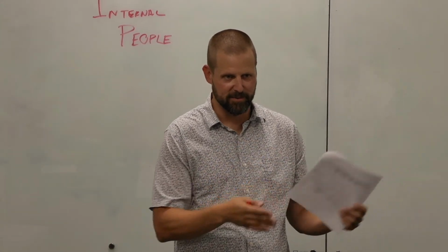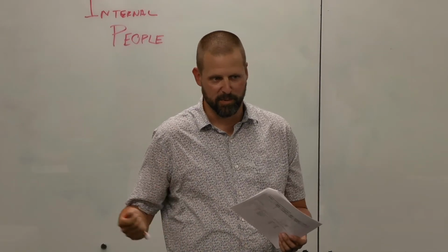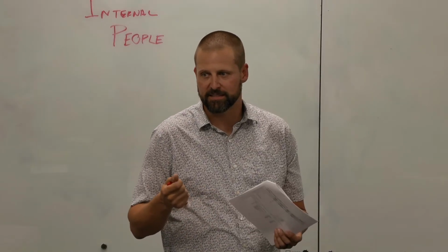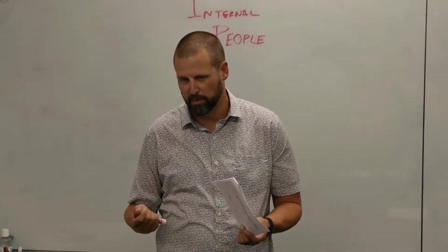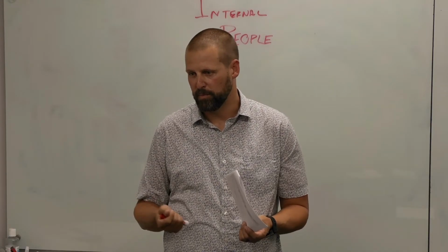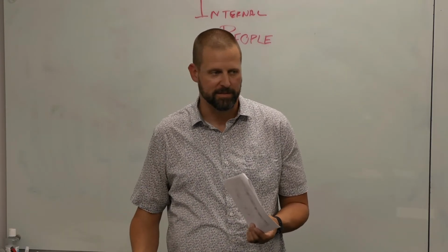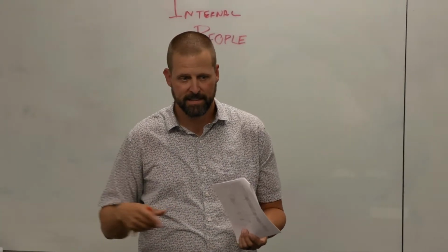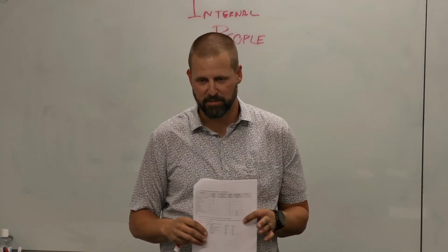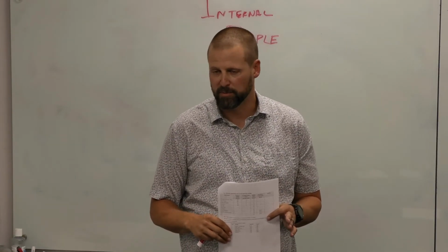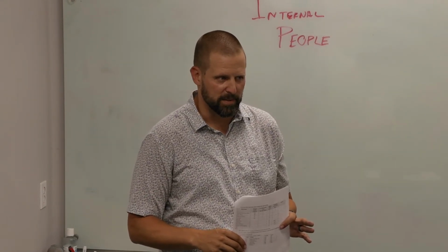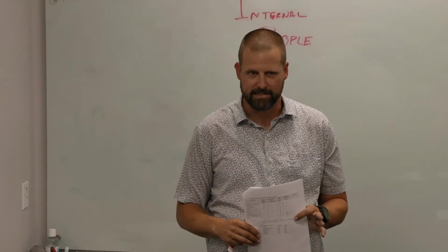So that's the activity level, and then how do we turn the activity level into BTUs? We count the number of people. How we do that is we usually do like 100 square feet per person for an office, or we put one or two people in an office depending on how many chairs there are. In a room like this, we might count the chairs. And then we multiply that by 200 to get the sensible load, and we multiply it by 250 to get the latent load. Does that make sense for people? Okay.